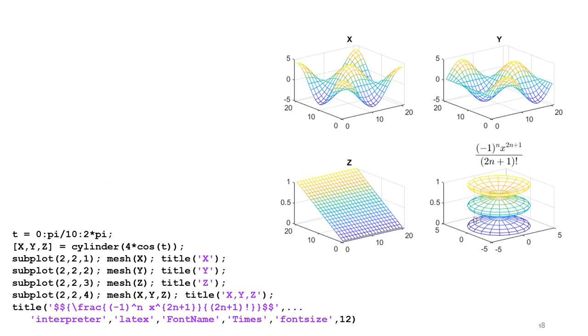Also, you can plot or show a surface by using the command called mesh. If you have a matrix and you would like to visualize this matrix in 3 dimensions, you can say mesh x, mesh y, mesh z, and this is a way that you can do the mesh for the 3 of them. Actually, mesh x here will produce a plot like this one, and then this one, and then z, now x, y, z will be accumulated this way.